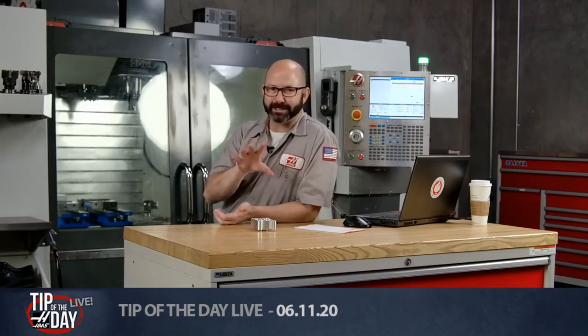Yeah. So with the orient spindle thing, I think if you use an M19, there might be an issue with that. I'll have to look it up and see what's going on with that particular case. Why can't you just use an M19 R180, and then put a G14 in front of it and have it be the same as an M119, which is the spindle orientation command for the sub-spindle, R180. So we can take a look at that. Getting all those things to line up perfectly is unique.